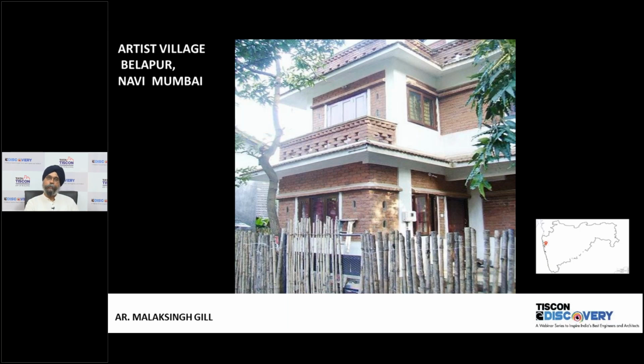And we did not plaster the walls once again because it's not required. And if you see on the first floor where there is a higher wind velocity and the rains do hit the wall, we have plastered the wall up to 3 feet height to protect the walls from the rain. But everything else is unplastered.